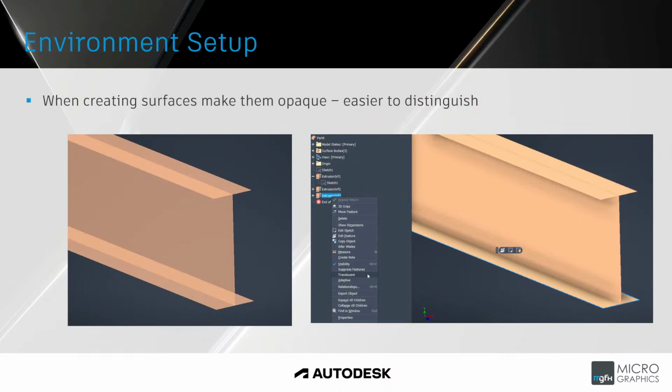One thing you can do as well, when you're working with these surfaces, is that sometimes you've got lots of parts and lots of surfaces, and it's very difficult to see what's going on because they're see-through. So what you can do is make them not see-through, or opaque. To do that, you select the surfaces in your part model and take off translucent. Then you can see on the right-hand side it actually looks like it's not see-through. It looks like a part. It's a bit easier to see.